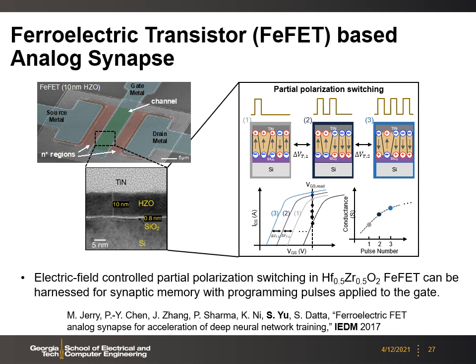We want to claim that the ferroelectric transistor FeFET can meet most of the requirements in the previous slide, probably except the programming voltage. Here we want to show a pioneering work by my collaborator, Professor Suman Datta's group at the University of Notre Dame. They published the first analog synapse based on the FeFET in IEDM 2017. Here the transistor is an n-channel transistor based on the HZO gate stack.